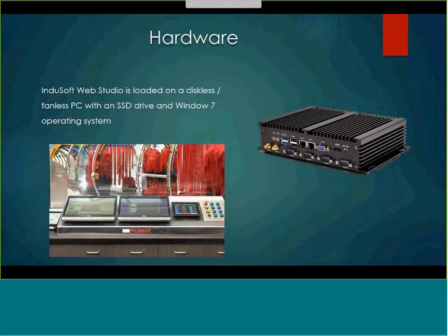From a hardware standpoint, we've loaded up InduSoft on a diskless, fanless PC. We use solid-state drives on a Windows 7 operating system. Typically, that little unit will be mounted inside one of our control panels. It doesn't have to be. It can be mounted somewhere else within our network. We set up, and we'll talk about this a little bit later too, a little Ethernet TCP/IP network that's unique to our control there with fixed addressing.